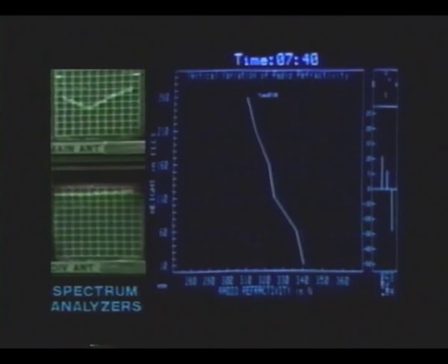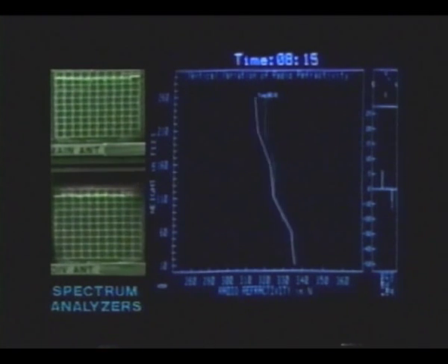Now, sunrise has caused a warming of the Earth's surface, causing a dispersion of the refractive layers. Our time-lapse is again accelerated between 8 a.m. and noon. The Earth's surface continues to warm, becoming a heat source once again. This reestablishes the vertical mixing within the atmosphere and disperses the temperature and moisture gradient that formed during the early morning hours. With this vertical mixing, the refractivity gradient returns to a normal condition, and the clear air fading previously observed on the received spectrums has ceased.